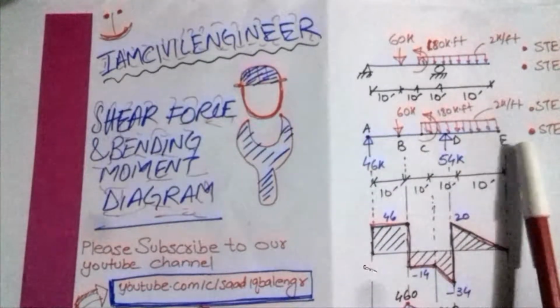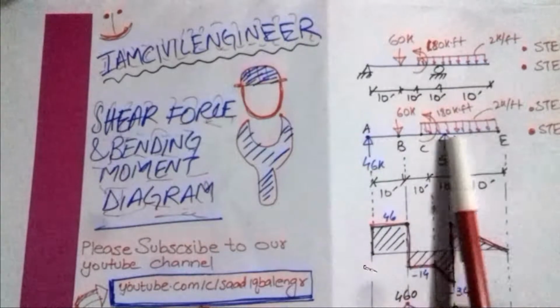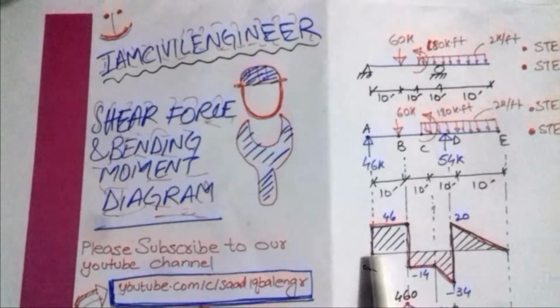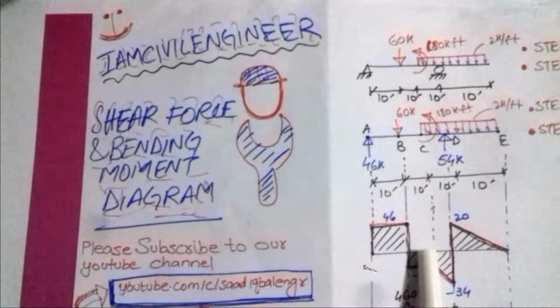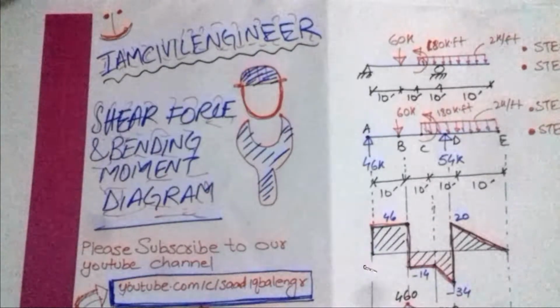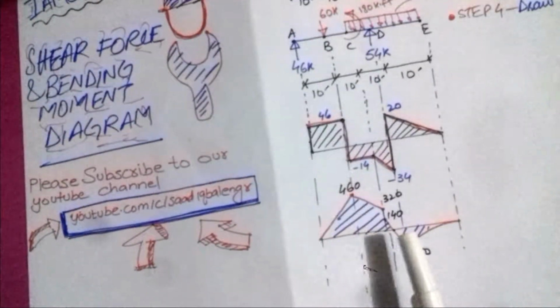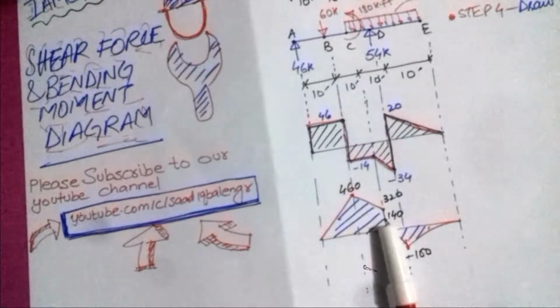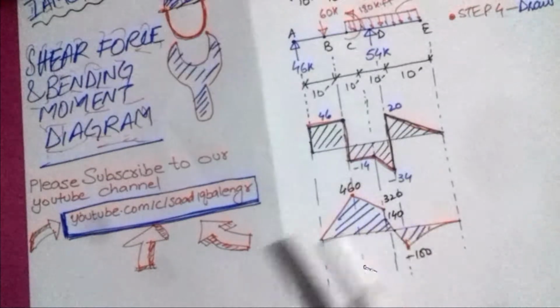length of the member. So if this is the length of the member, the length of the beam, then the shear force diagram shows the variation of the shear force along the length of the member, and similarly the bending moment diagram depicts the variation of bending moment along the length of the member.